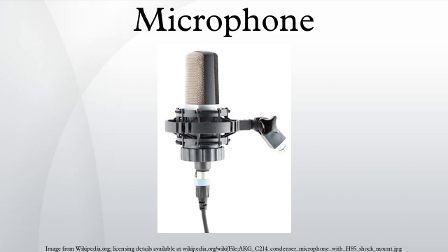This preamplifier is frequently phantom-powered in sound reinforcement and studio applications. Monophonic microphones designed for personal computer use, sometimes called multimedia microphones, use a 3.5 mm plug, usually without power. For stereo, the ring, instead of carrying the signal for a second channel, carries power via a resistor from a 5V supply in the computer.